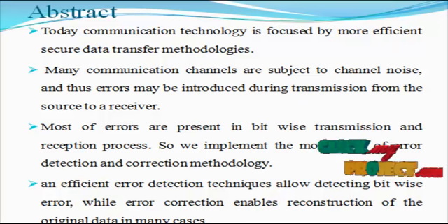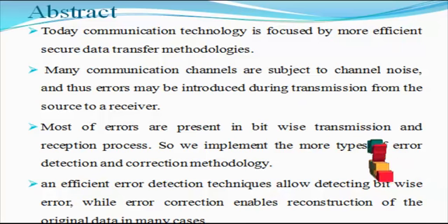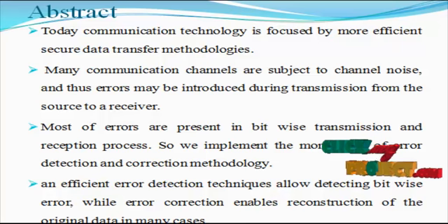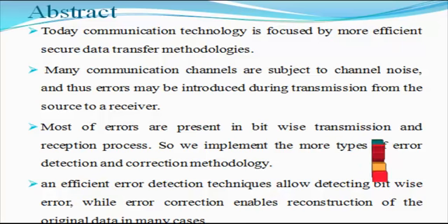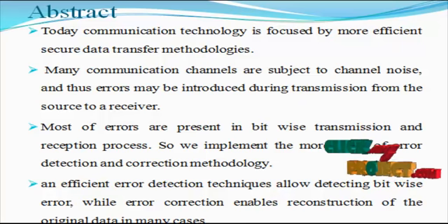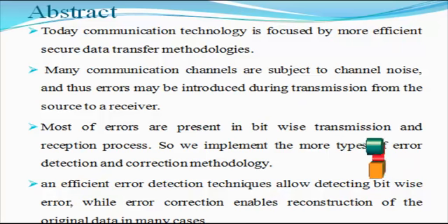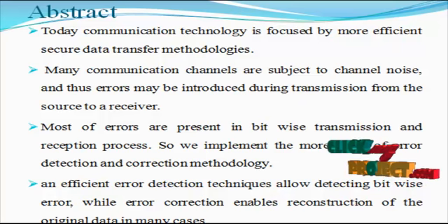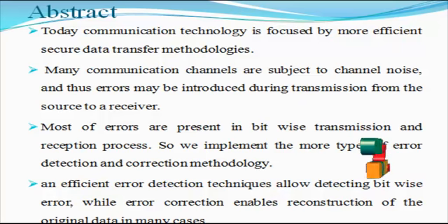The memory device continues to operate correctly but has the wrong value in the affected cell. Dealing with soft errors uses a per-word parity bit or more advanced error correcting codes. Bloom filters provide a fast and effective way to check whether a given element belongs to a set. Bloom filters are used in numerous applications, for example in communication and networking.